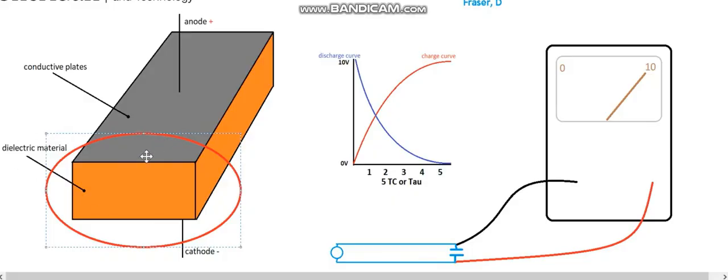So what normally will happen is there will be a paper and a foil and a dielectric material and a foil and a paper, and then they roll it up. Think of taking a sheet of paper out of the printer and having a conductive plate on one side with an insulation and a conductive plate on the other side with some insulation, and then just rolling it up. And that's basically it, capacitors look like cylinders. If you've ever seen working capacitors,